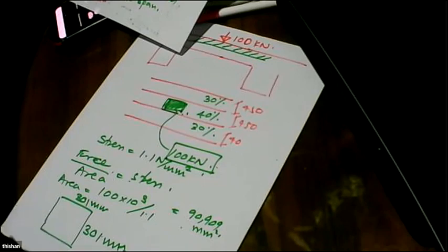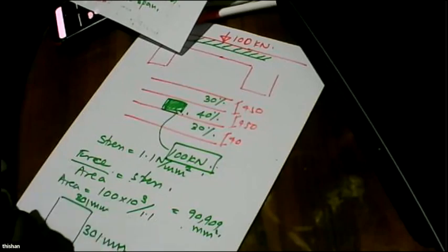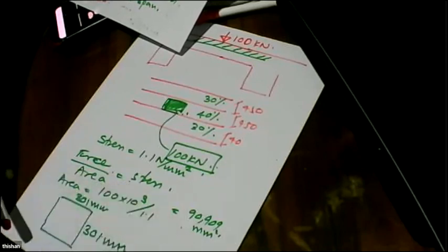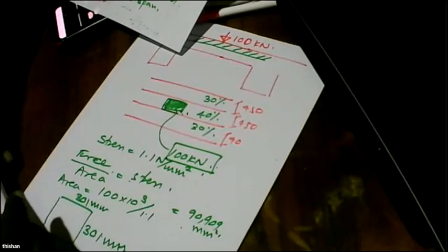It's very important. Otherwise, if you try to design for 100 kilonewton, you will find you need an enormous amount of reinforcement in the top slab. So you have to always think how much load distribution could take place because we are going to have a number of panels side by side. And so we have done testing. We have looked at the load distribution.